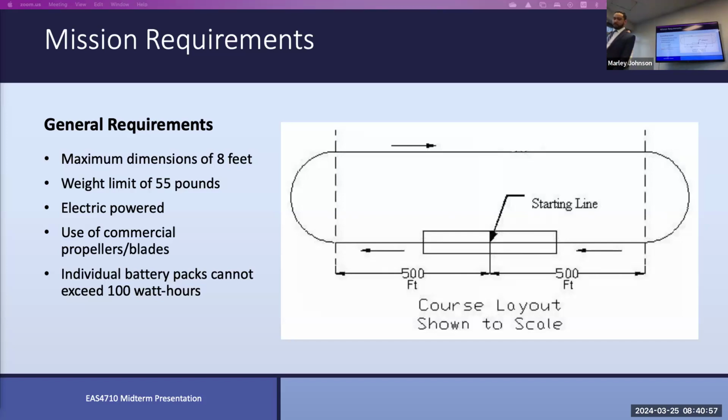So obviously, on to the part you're expecting is the test flight. In our test flight, our aircraft is required to complete a roll and takeoff within 40 feet. And it is required to only use the batteries on board. Once in the air, our aircraft will fly 500 feet to the first marker right here, where it can initiate the first turn and begin following the course around for 3 laps.